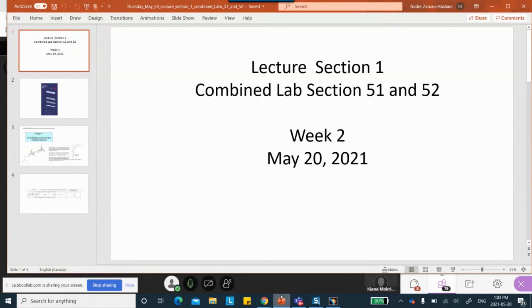Yes. So would you be able to use a restraint, a point? That's going to be tough. If you don't use symmetry, those side planes, it's going to be harder to do because it's free to move as a rigid body.